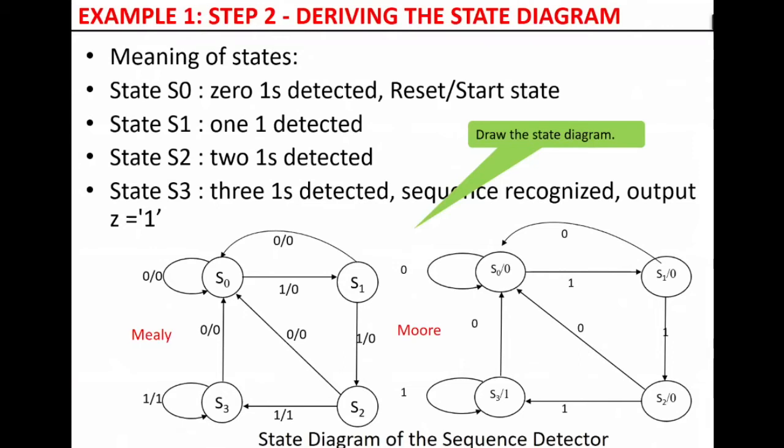Okay. This doesn't necessarily mean that the Moore has more states. It's just in some specific circumstances. You have to check. In this case, they've got equal number of states. But in most cases, the Mealy always has less. The difference between Moore and Mealy is one affects the change after the clock, the other one before, but it's not necessarily that it must have more states. It's not compulsory. In this case, they've got the same states.